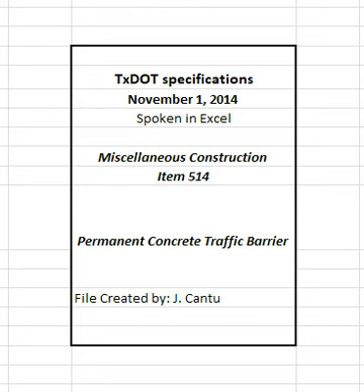Multi-project fabrication plants, as defined in Item 424, precast concrete structural members, fabrication, that produce concrete traffic barrier must be qualified in accordance with DMS 7350, qualification procedure for multi-project fabrication plants of precast concrete traffic barrier. See the department's MPL for approved fabricators. Construct drilled shaft foundations in accordance with Item 416, drilled shaft foundations, when required. Construct barrier in accordance with Item 420, concrete substructures.